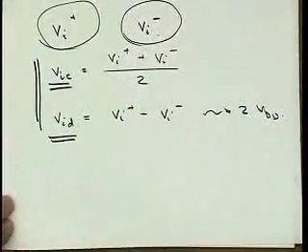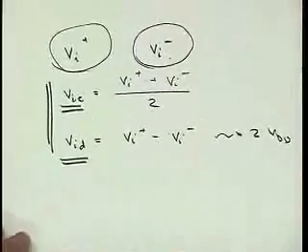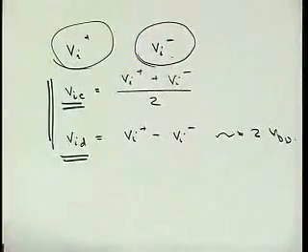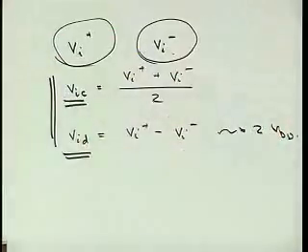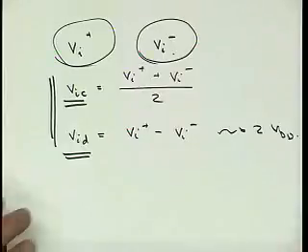The problem with that solution is that first of all, it takes all sorts of circuits, but more importantly, impedances really don't get translated properly anymore. If we want to know the differential input or output impedance of the amplifier, well, if we produce the differential output voltage using ideal sources, the output impedance looking at the other end of the generated VD is now going to be the output impedance of the ideal sources, presumably 0, right? And it's got nothing to do with our amplifier.